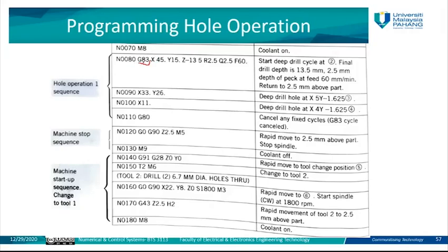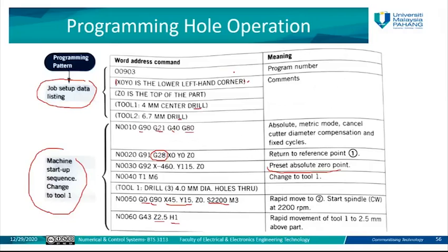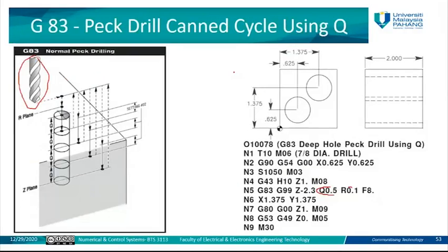Then we start to perform the drill cycle, which is G83. When we talk about G83, we are talking about deep holes, which require defining different parameters. In addition to the coordinate, you need to define the R plane, also the Q value, and also the feed rate, as we see in this operation here for the big drill. The same here, the same as this operation.